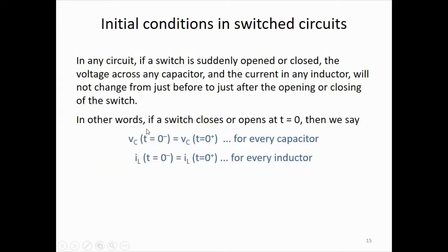Therefore, we make this statement which we will use in all subsequent work, in fact when we do the next chapter in the next lecture. So let me just read this. If in any circuit a switch is suddenly opened or closed, as in that simple example we had, then the voltage across any capacitor and the current in any inductor in that circuit will not change from just before to just after the opening or closing of the switch.